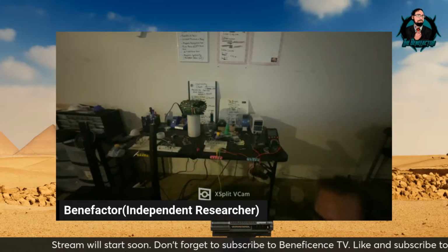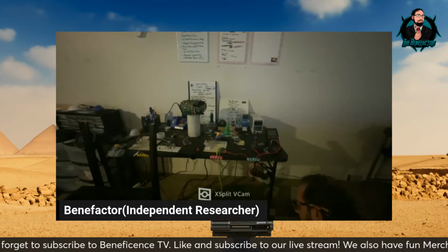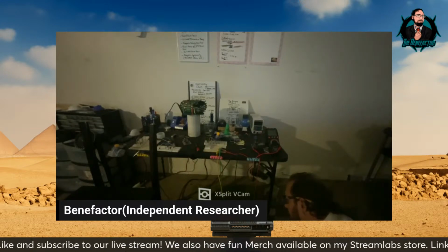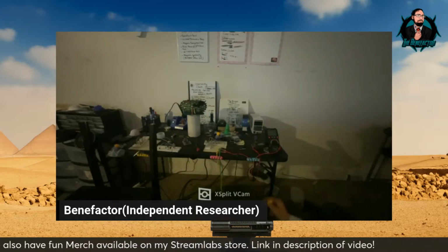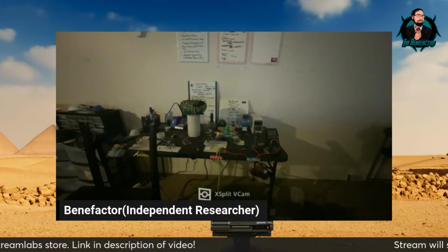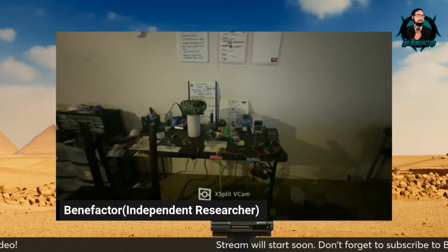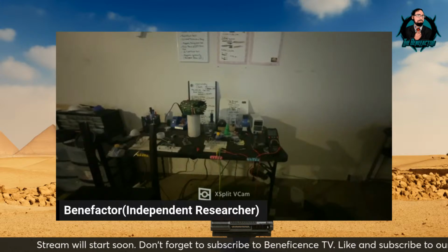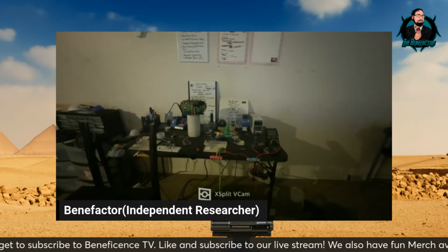I think he's not charging the coil long enough to get the DC from one end to the other. It could be both, and that's the duty cycle. I was telling him to put the duty cycle lower before on the Fireball coil. I didn't have any problem running at a low duty cycle with DC, but I had my voltage up around 27 volts, getting it from batteries, not power supplies. That's what I'm saying. It's rapidly on and off so fast that it thinks it's always on. Yeah, but these could be 5 or 10 volts. And Mike, remember, the higher the voltage, the better.